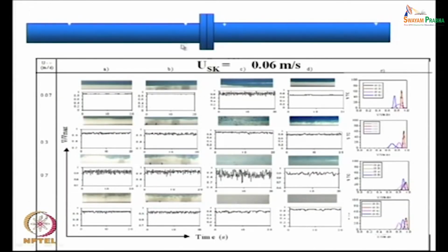This is another particular case which I would like to show, a very interesting case when we were studying kerosene water flows through the orifice meter. In this case, if you observe here, what did we find? We had started with a smooth stratified flow. The orifice is located at this particular position. Just after the orifice, what happened? It became a completely dispersed flow situation, and more or less it ended up being a 3-layer flow pattern.